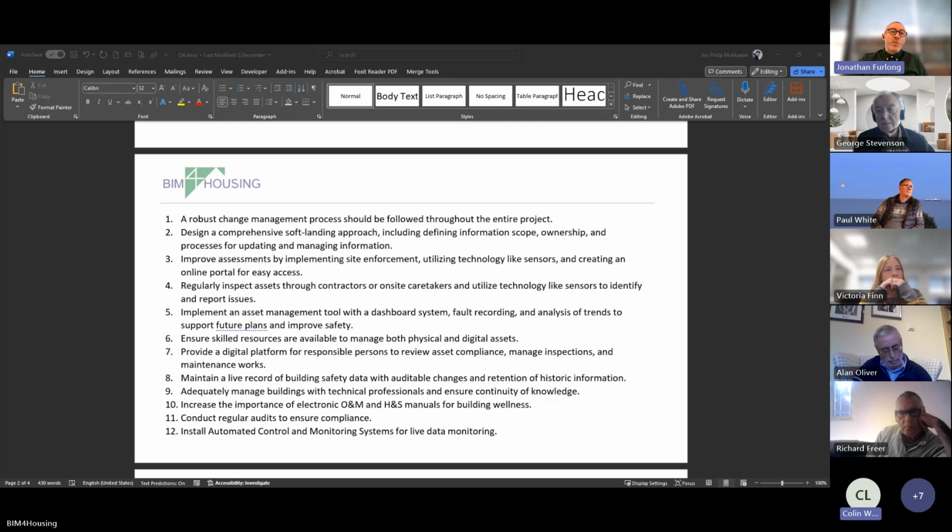That doesn't mean they're in any way qualified to service a lift or to do any of the more complicated items on a lift, but it should be very easy on a weekly basis for caretakers in the building to test whether the lift is operational from a fire perspective. It's turning on the fire alarm, testing the trigger on level 1 and seeing what happens. So although there is a huge amount of information in making sure a safety case is up to date, there are two parts. There's the really simple information, which is the up-to-date stuff, and then there is the more in-depth testing, which is the next stage.